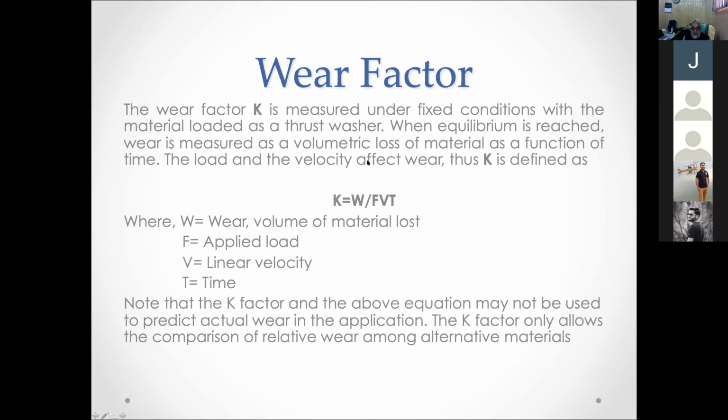So, wear factor. You have to know two things very essential for the design of bearings. That means two material properties must be known to you. What are those two material properties you must know? One is the PV factor and the coefficient of friction with it. The second is the wear factor.